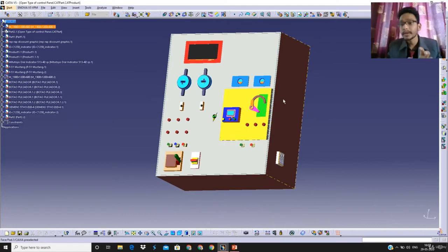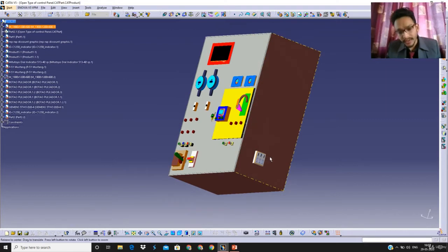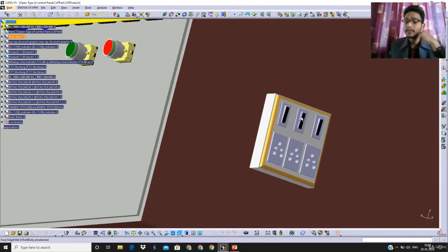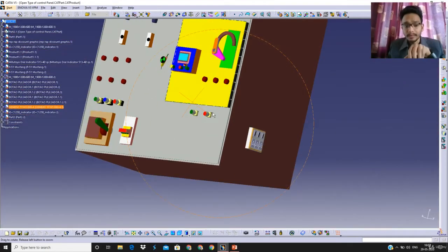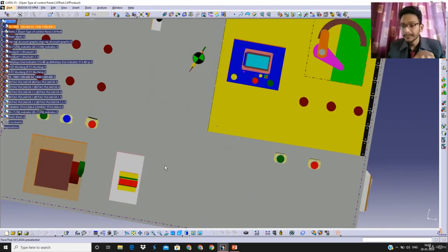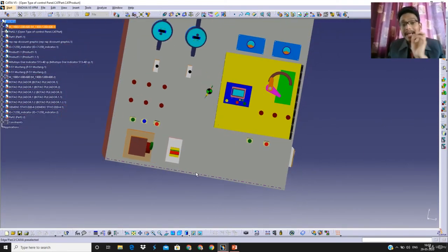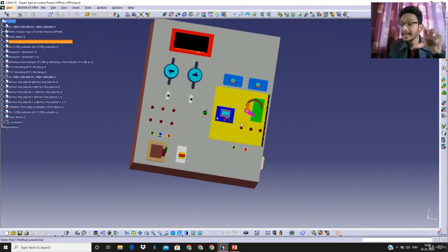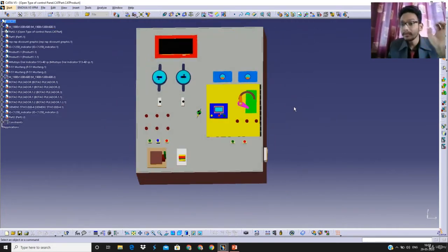So first of all, here you can see at the right side of our panel there is one type of panel box, or we can say your AC connector along with the switches. Okay, so it's a 3-pin socket. You have to plug your instrument panel from this system. Once you get the power supply, you have to turn on this MCB. Once you turn on the MCB, it helps to protect your system by automatically disconnecting it in any abnormal condition. So your control panel will get protected, isolating the device itself from the supply.